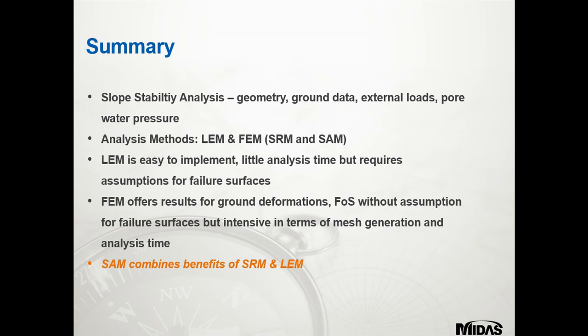So now just give you a summary of what we've just done in the modelling space. So we've had accuracy of the results in slope stability analysis, and it depends on the geometry in your modelling space, the material properties for the ground and also the structural elements, loads and the correct pore water pressure profile. The analysis can be performed by either limit equilibrium or finite element methods.